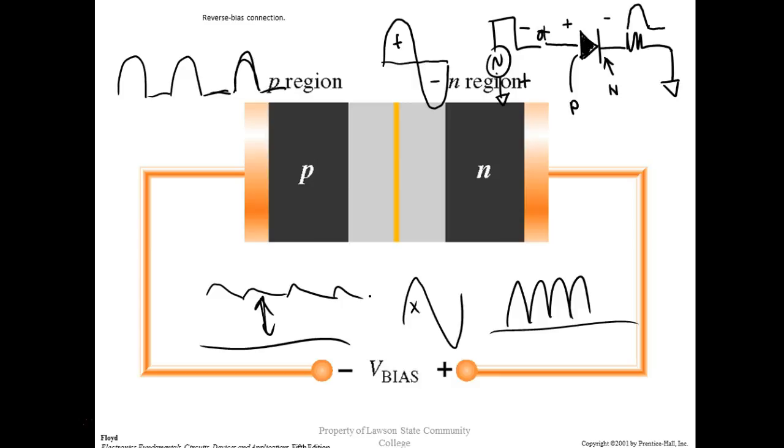But when this side here goes out, you can't fix it. So mostly when a switching power supply goes out, it's so complex that it's almost impossible to troubleshoot. So usually when a switching power supply goes bad, you just do what? Replace it. And that's why they encapsulate these things. If you open this up, it's going to be a big piece of epoxy in there. You can't even get to the power supply. You can't get to the diodes or anything. But I guarantee you there's diodes in here.